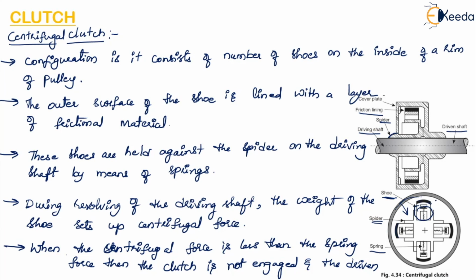The shoe will start moving outward, come in contact with the driven member, and get pressed against its surface, and the driven shaft will start rotating. Only then will the shoe come out and press against the driven member.